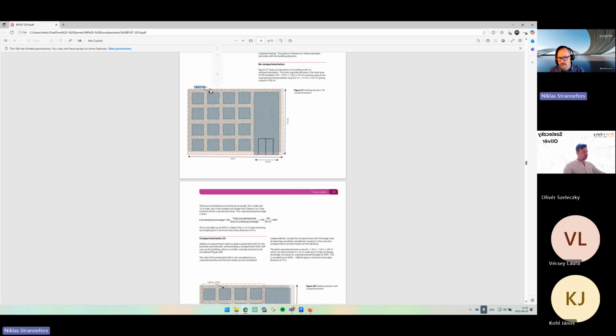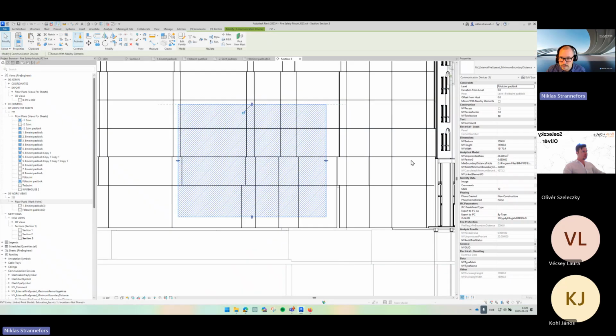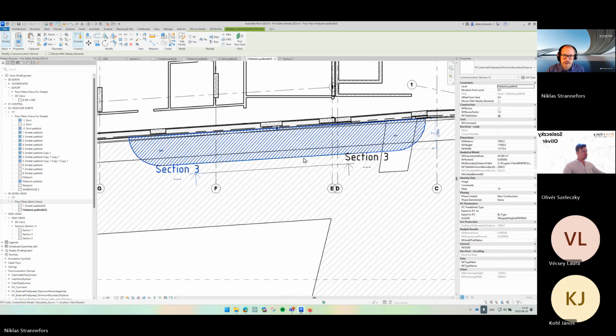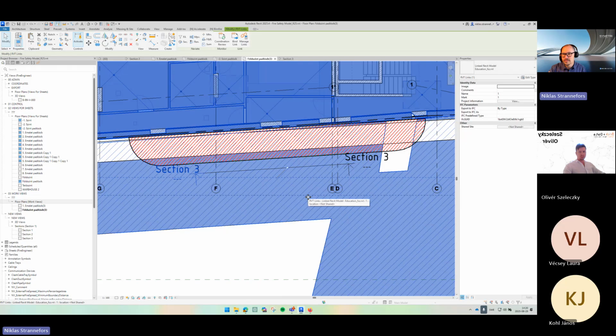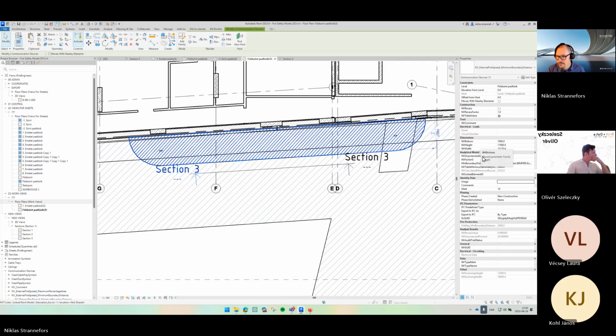And then we need to calculate how many openings they have. These are where they have like 1 by 1.8 meters times 0.8 by 0.8 meters. We can make something up. It doesn't really matter, but it's more about how many square meters of openings we have in this facade. That would be this one, unprotected. I'm making it 45 square meters. Why not? And then based on that table, it will change the thickness and distance. You get the minimum based on the table value.